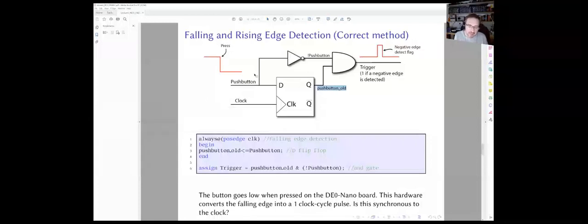So just think about that for a while. And this is also why we have an AND gate here, because if both of them are 1 for a short amount of time, that would actually give us a pulse. That pulse would go high when both of the inputs to the AND gate are 1. Otherwise, in all other conditions, it's 0. So this is a very neat way of doing falling edge detection. To do rising edge detection is something slightly different, but a very similar concept.